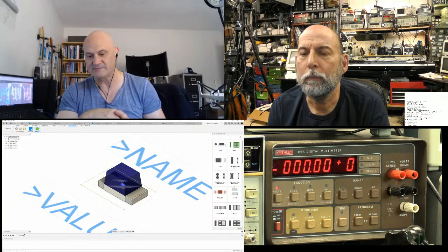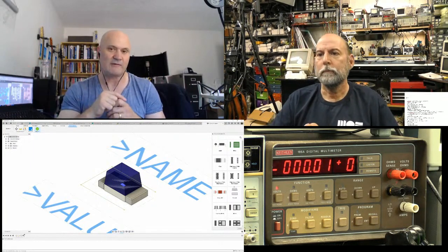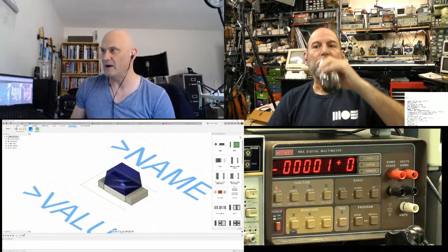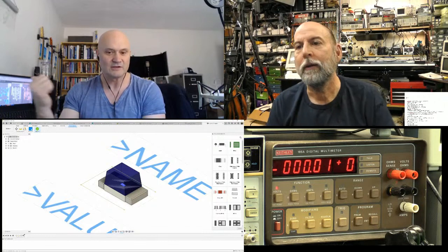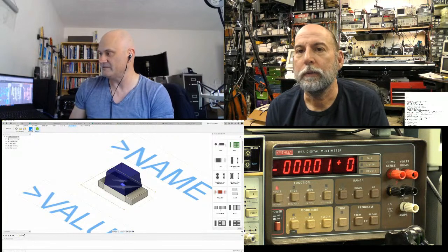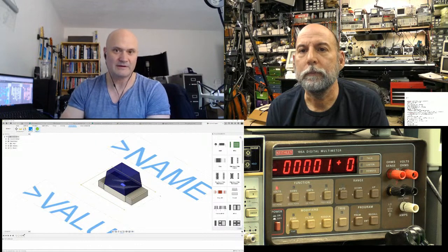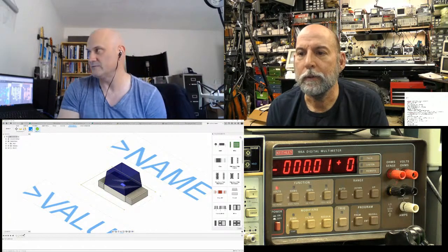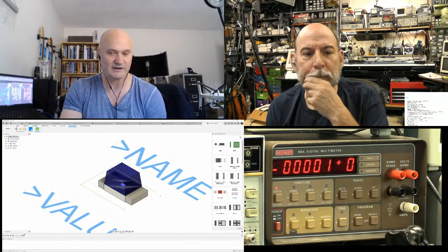Altium just released on their website a collaboration between the Fusion MCAD and Altium Designer, so you can push a board that way and get all your models in Fusion and then make your enclosure in Fusion. But even if you're using KiCad or some other tool and you want to generate STEP models, use this package generator in the free version, and these 3D models can be exported to STEP, so you can use them in any other tool. It's worth having Fusion alone just for generating the models for your parts if you're not also designing schematics and PCBs.